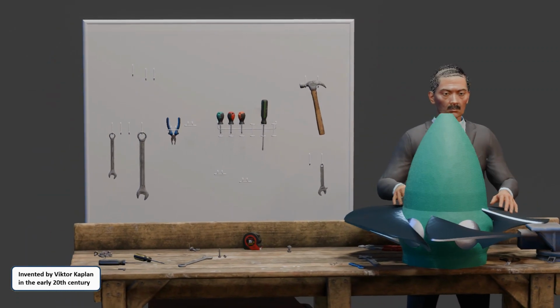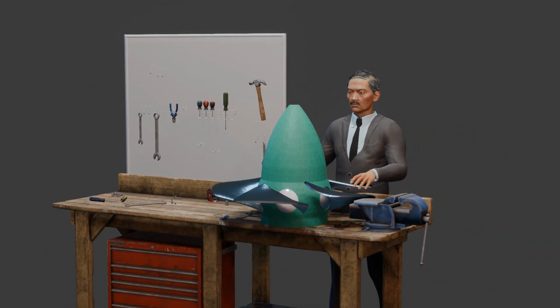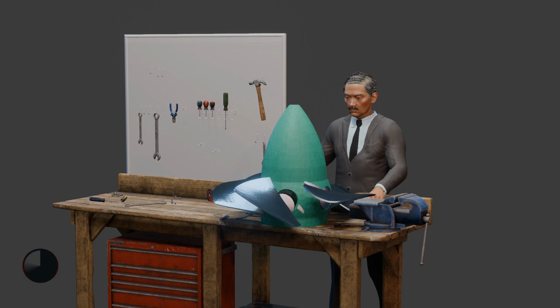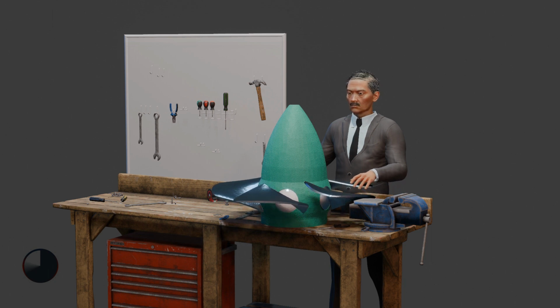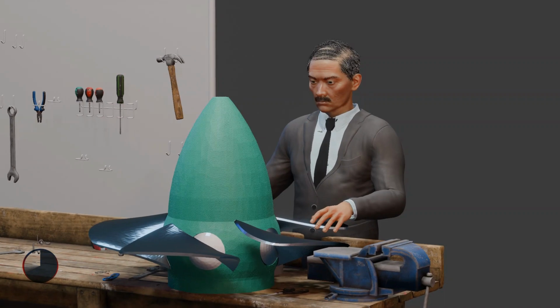Invented by Austrian engineer Victor Kaplan in the early 20th century, this turbine is specifically designed to harness the power of low to medium head water sources, making it ideal for locations with moderate water flow. Its distinguishing feature lies in the adjustable blades, or propeller, which can be rotated to optimize performance under varying flow conditions. This flexibility allows the Kaplan turbine to deliver exceptional efficiency and power generation across a wide range of water